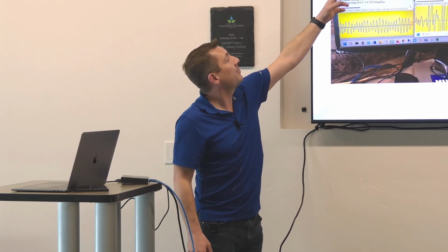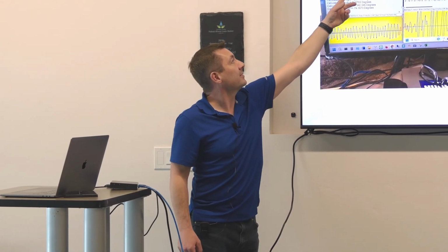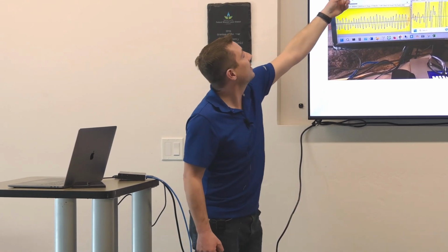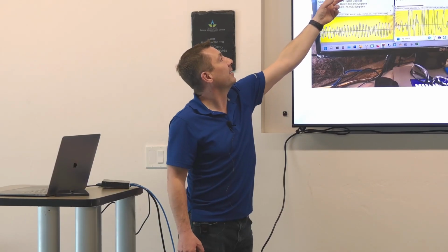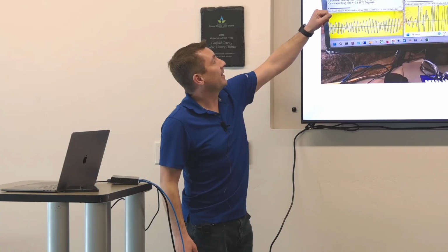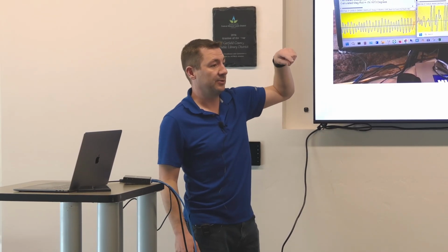We can send up real-time inclination, based on the 0.98. We can plug that in and get our inclination in real time while we're drilling. So we don't have to stop and take a survey, because sometimes if we're starting to do the build and we're building up faster than we want to, we'll stop the operation and then go to sliding, say if we need to slide down or up or left or right. This is what we call a tool face packet. They're constantly coming up all the time, so we don't have to stop and take a survey.